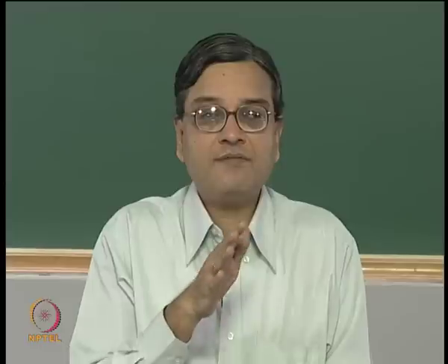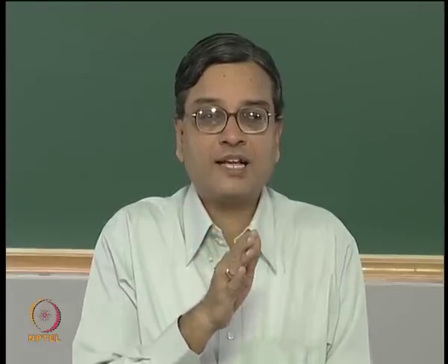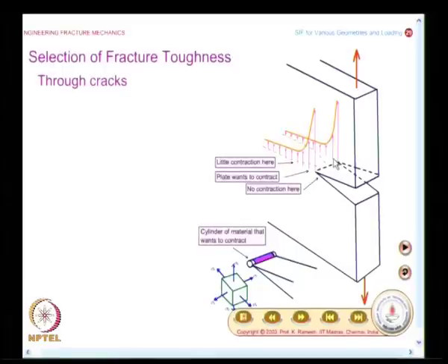If the crack is blunt at the crack tip, you will have sigma x as 0. For the purpose of discussion, let us consider the crack tip is sharp. So, you have sigma x equal to sigma y, and if the plate is sufficiently thick, you will also have stresses developed in the thickness direction of the plate, and that is given as nu times (sigma x plus sigma y).